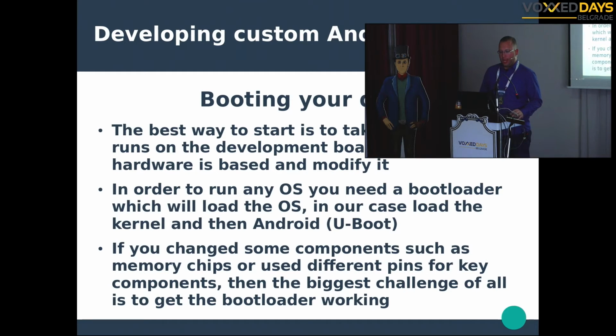So if you changed some components on your board, so you did not make it the same as the development board, that's where it's going to trick you and take you a lot of time. And that's why I say it's difficult to first boot. When you get the device and you use the bootloader and try to run it, usually you do not have any output to see if it's working.